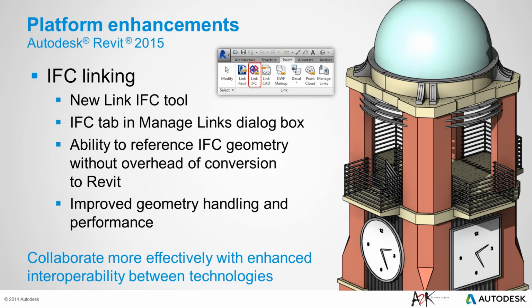You can link an IFC file to the current project using the new Link IFC tool. If you later change the IFC file and reload, the project updates to reflect the changes. When opening an IFC file, you can specify whether elements join automatically, that is, walls to walls or walls to columns. In the Open IFC File dialog, the Auto Join Elements option is turned on by default. Turning this option off provides more control over the results and may improve performance during the import process.